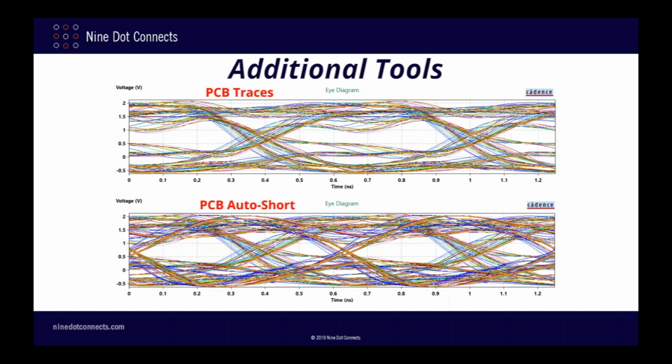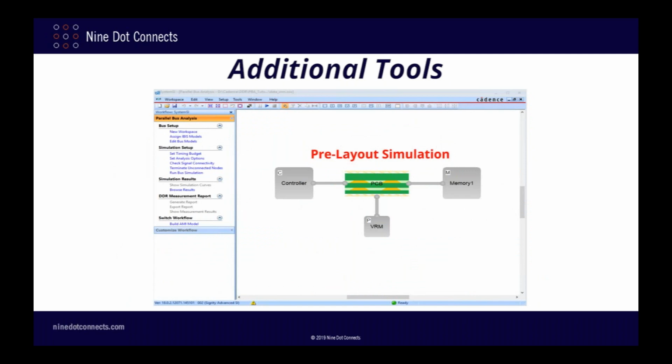There is also another useful tool known as pre-layout simulation. While it might not seem to make sense to simulate the design without even having the board layout done, it can actually provide extremely useful feedback about the design functionality early enough to fix any problems before spending time and money doing layout. You can then define the transmission line parameters any way you want, essentially emulating what you think the PCB will end up like before you do the actual layout. In the interest of time, I will not actually demonstrate this here, however.